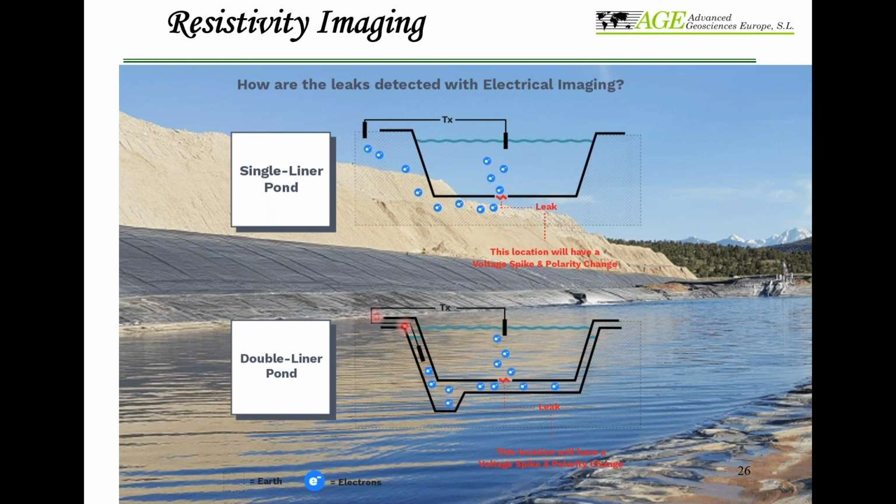If you have two liners, the outside current electrode will be between the liners, where the leakage can be controlled, because current will flow through from here. Where the current crosses, the voltage will be 0, and you will have negative and positive voltage around it. So that's the point you're trying to find.